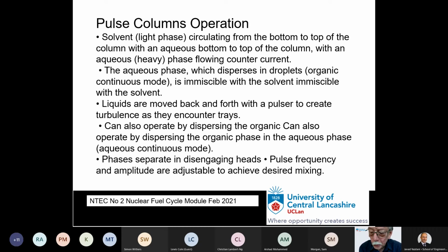So where you've got no moving parts, and one of the reasons that Thorpe was a fairly high building is because it didn't pump any of its radioactive liquids. If the pump failed, then how do you move liquid from A to B, particularly if B is downstream? What actually happened at Thorpe, of course, was most of the movement of liquids was by gravitational force.